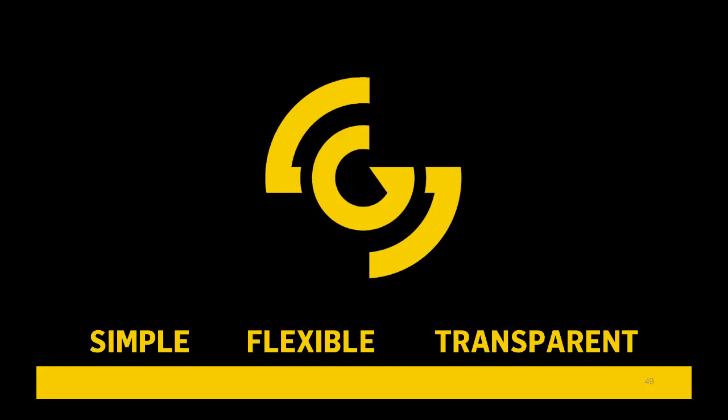Let me scroll back down here. As far as how close to the stop bar the zones should be drawn, you want to draw your zones basically like you would have a loop in the road. So you really want to mimic a loop in the road, so that as vehicles travel through the lanes, they're actually traveling over the zone where we expect it to be. So you want to draw your zones just like you would in a regular, standard stop bar scenario.